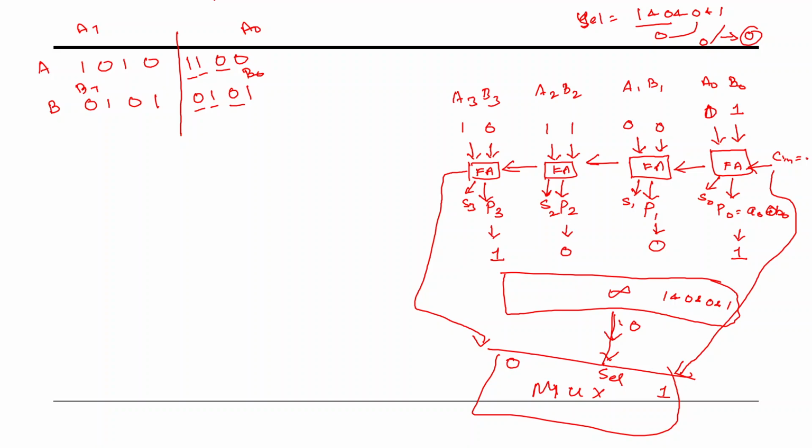So now what happens over here? So to select this carry, right? What's the carry here? Compute over here. 0, 1 is going to be 1. 0, 0, 0. 1, 1 means 1. And carry is 1. 1, 1 means sum is 1 and carry is 1. So the carry output, this C out, is 1. This 1 is selected. So the C out is 1 now here.